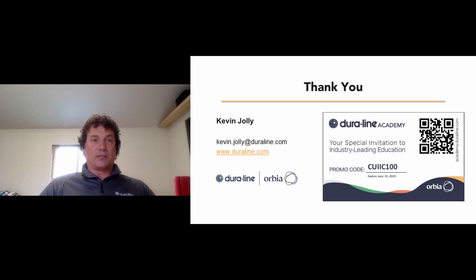There are other things to consider, like the number of 90s and bends. It can handle a lot of bends. We have a test track in our Bracebridge facility in Ontario, and for every kilometer there are 98 90-degree bends, and we're able to jet that kilometer with multiple different cables.